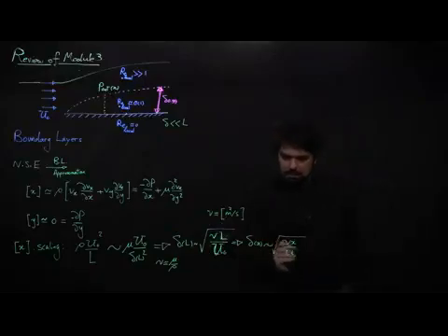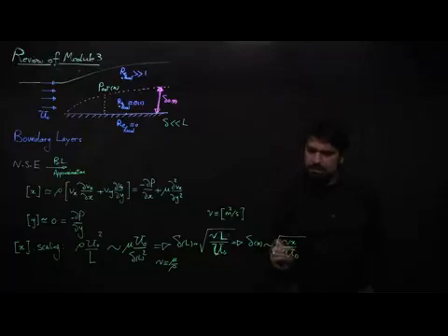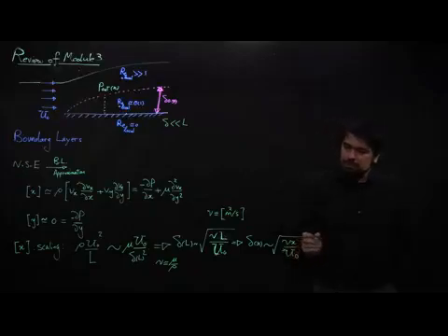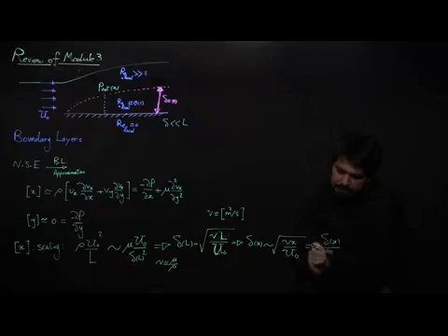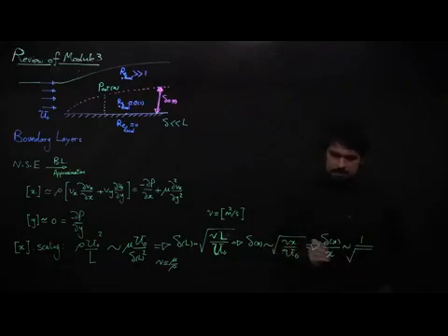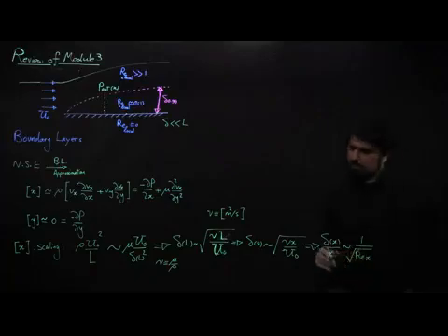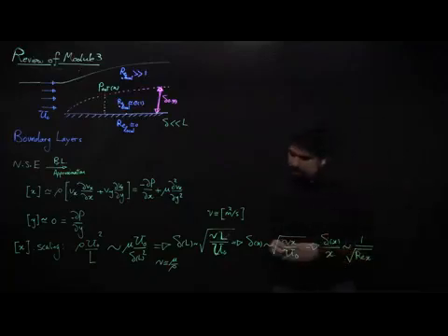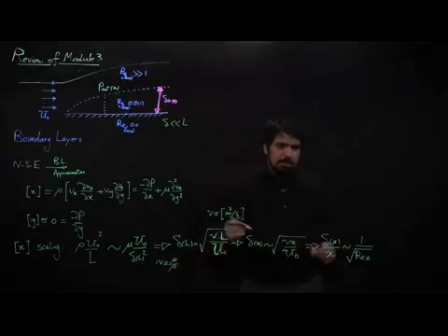And the same thing here. I can replace L with x, so I get delta as a function of x goes as a square root of nu x over u0. And you can simplify this, make it dimensionless. Delta as a function of x divided by x will go as 1 divided by a square root of Reynolds number, and let's actually do that. Yes, the square root of Reynolds based on x. So that's how we find the scalings in this phenomenon.